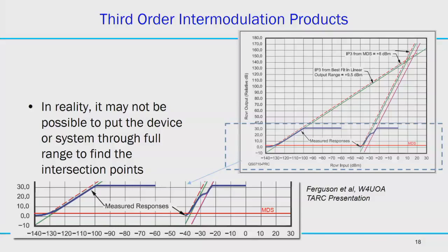So how do we deal with these intercept points? We just use the linear curves and extrapolate to find the intercept point, because it is one consistent way of measuring and quantifying. That's the only reason. The actual intercept point will be meaningless for real powers, because you will never reach that point in practice, as most devices will get killed by that time. So just be mindful when you plot something and it comes up like that. Don't think that you got something wrong, because it's just a device that will always operate over a narrow range.